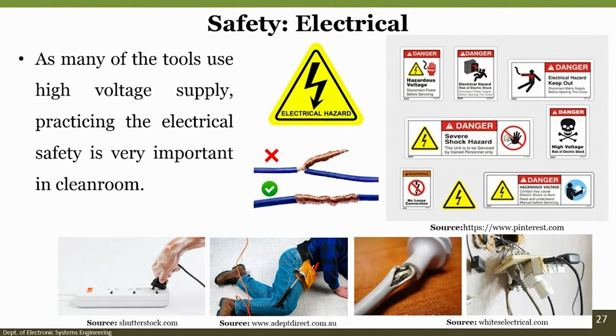In fact, wherever you are working in your lab environment, make sure that all the safety issues are taken care of. As many of the tools use high voltage supply, practicing electrical safety is extremely important. What you see here is absolutely not allowed. A wet hand is there, and we are using the power, and then you can see there is a dangling wire, absolutely not allowed. Cut wire, not allowed.